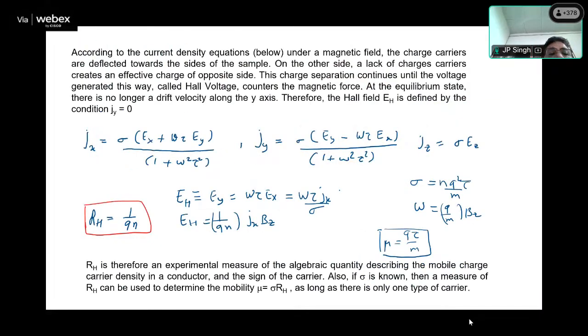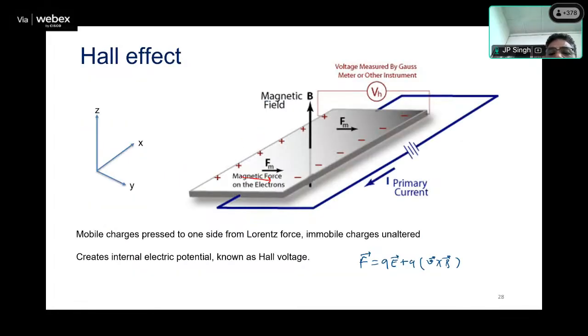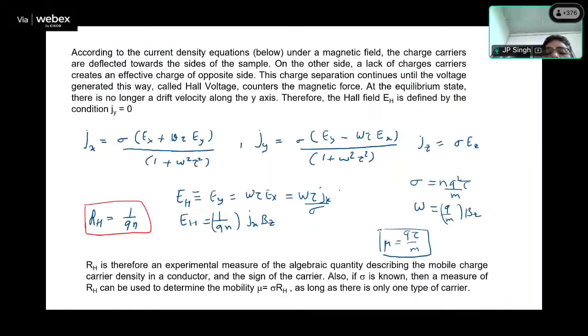So basically, now you see, because of that, the charges move widthwise. Charges are going to build up here, and when the charges build up, it means there is some current moving in this direction. I can say there is a current density in the y direction. Before that, the current was already moving. We had the current density in the x direction, and because of the magnetic field, it gets deflected, giving Jy. Because of that current, charges are going to be built up there.